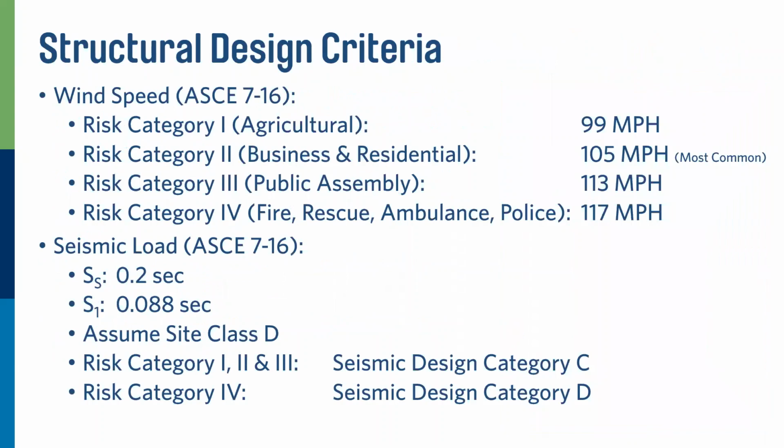So what are the design criteria? This is something that gets overlooked probably 99% of the time. There are structural design requirements. Just like when I designed this building we're in today, or your house, you have to design your house to meet the exact same criteria as your signs. Everything's got to be designed to meet these design codes. So a structural engineer will take these miles per hour and convert them to a pressure, a PSF, a pound per square foot. And then they know that's what they have to design your sign for.